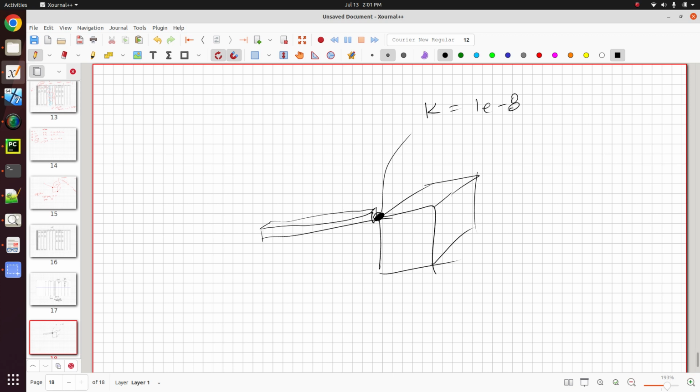I'm just exaggerating. If you're not careful, the stiffness ratio might be really small. So I think 1e negative 7 is the tolerance. If the stiffness ratios are really small for this degree of freedom, it will go ahead and constrain it. So here I'm using a fixed support icon to communicate that it's being supported here. So this is a problem, because it might actually remove degrees of freedom that you want.